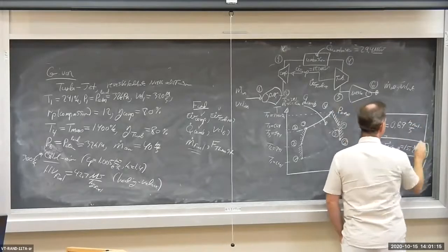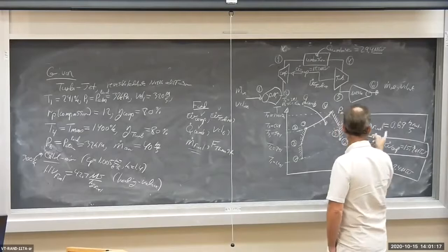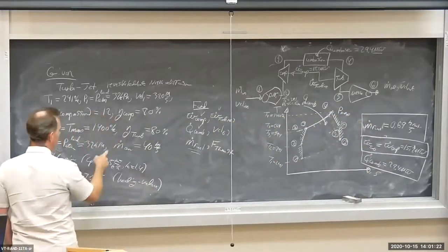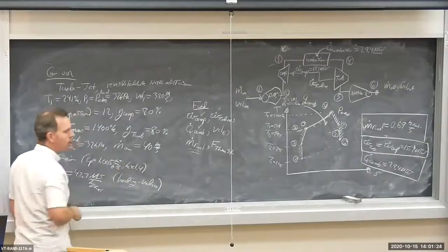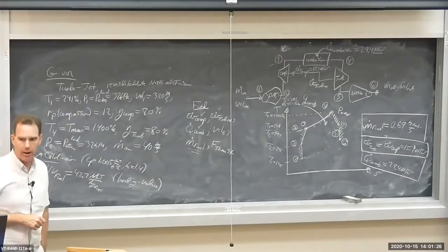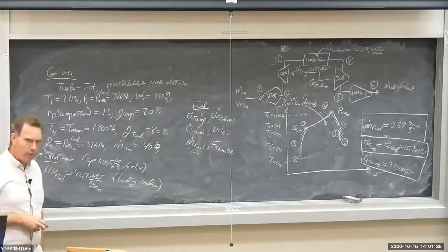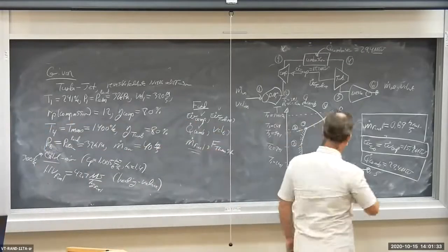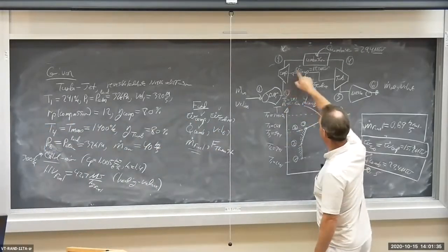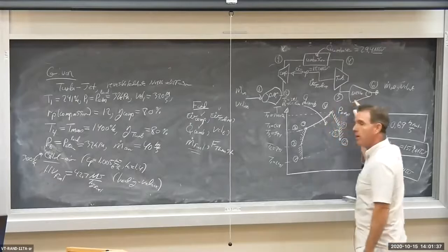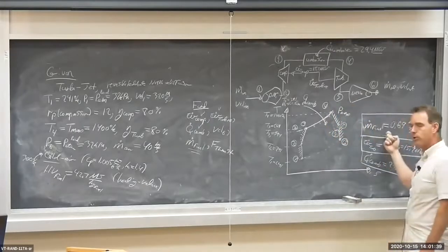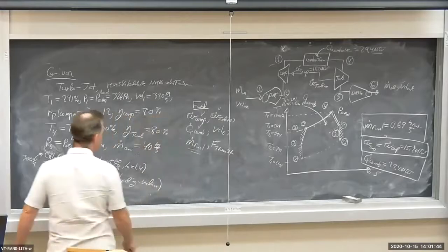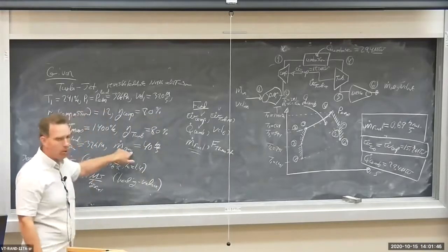By the way, 0.69 kilograms per second of fuel compared to 40 kilograms per second of intake air. Now you see why we assume M dot through the device is constant, the same in the diffuser, compressor, combustor, turbine, and nozzle, because the M dot of fuel required to heat up the air is so small compared to the airflow rate.